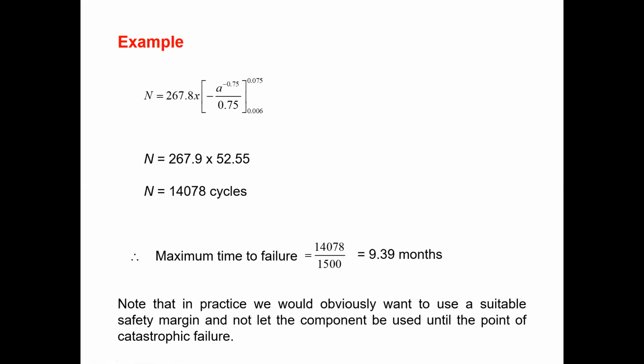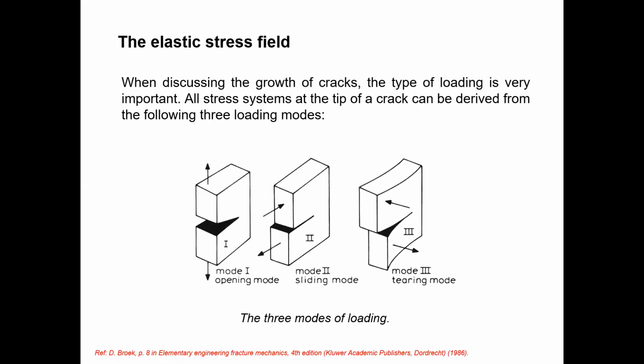So that's how we can deal with this kind of equation and this kind of question. I hope it's clear. And then we need to discuss crack growth with different types of loading condition. Basically there are 3 modes, and crack growth varies with the 3 modes. The first mode is opening mode. You can see in here the crack will open. When we apply the tensile load like this, the crack will open, so the crack can easily grow. We call it open mode or mode 1.